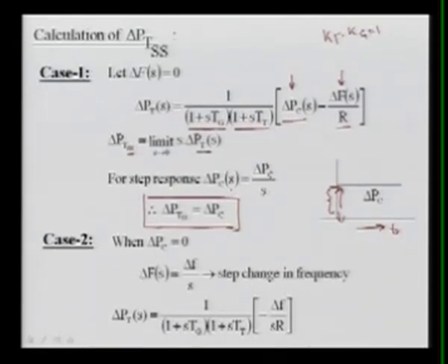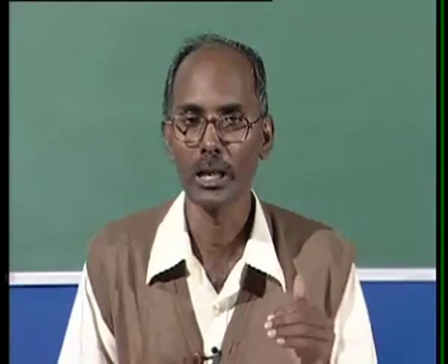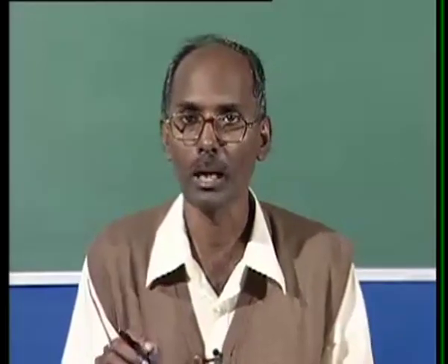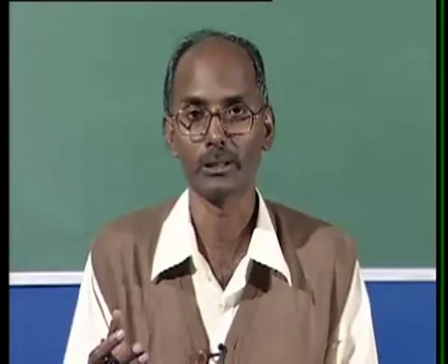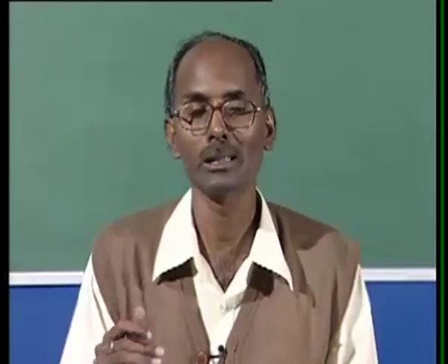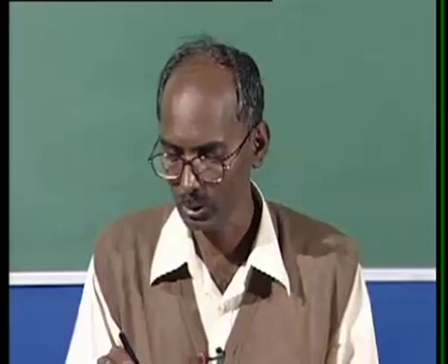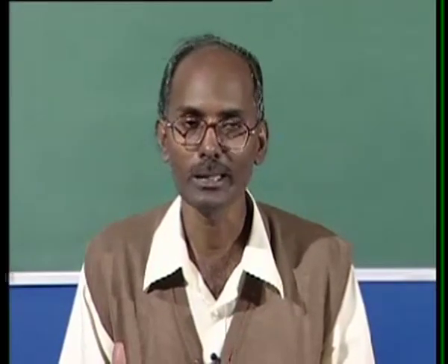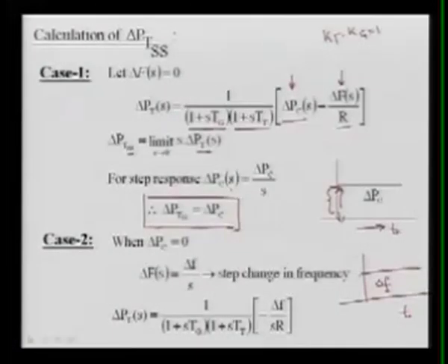In another case, let us suppose I don't want to change the P reference, that is the PC, meaning I don't want to give a raise or lower command. And the frequency is changed, meaning suddenly the system frequency changes, and again I am talking about a step change in the frequency. Here again I can say this is your time, and this is the change in frequency, your change in F. So this magnitude is changed. I want to see how much the turbine output power is going to change during the steady state condition. Here a sudden change means there will be some settling transient, and finally it will settle.